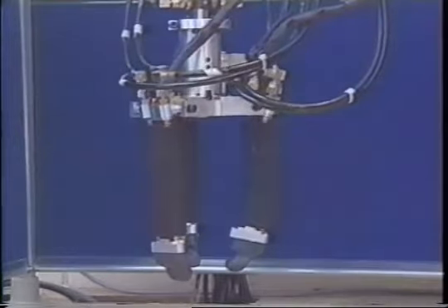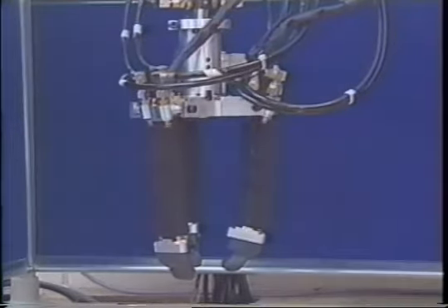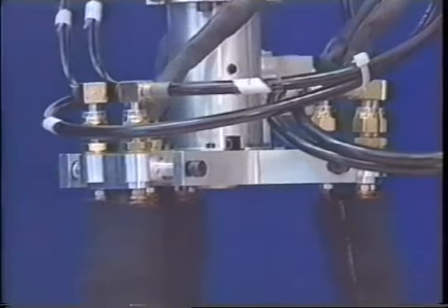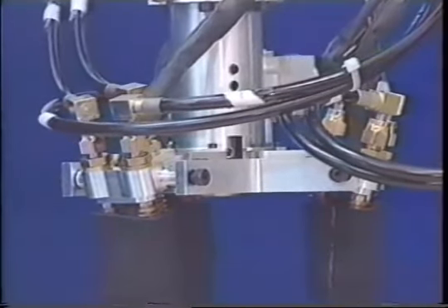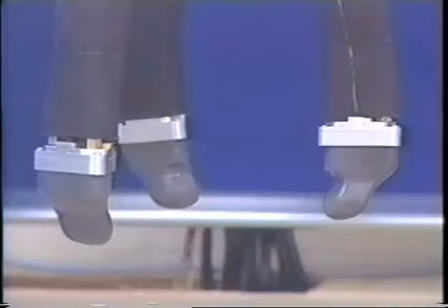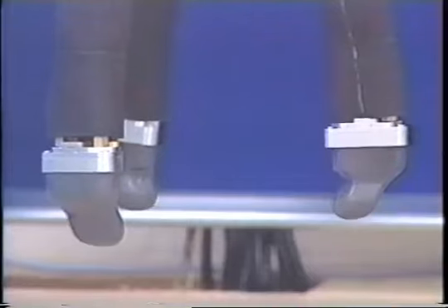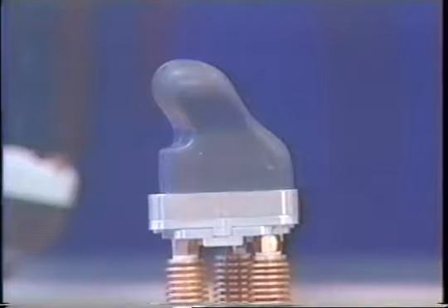For additional movement, a hydraulic knuckle mechanism is incorporated into each finger. With 40 degrees of angular rotation, objects between 10 and 150 millimeters can be grasped. The finger design is inherently pressure compensated for use at depth and has natural passive compliance for robustness.